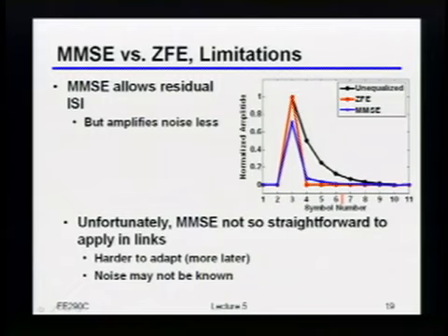If I make the SNR not super high and do an MMSE, you can see with this blue response that there's a little bit of residual ISI right there that I allowed, and maybe even a little bit left right there too. For this particular channel and the particular SNR I chose, on net mean squared error, it was better to leave that ISI than to amplify the noise and try to kill it. Does this make sense to everybody?